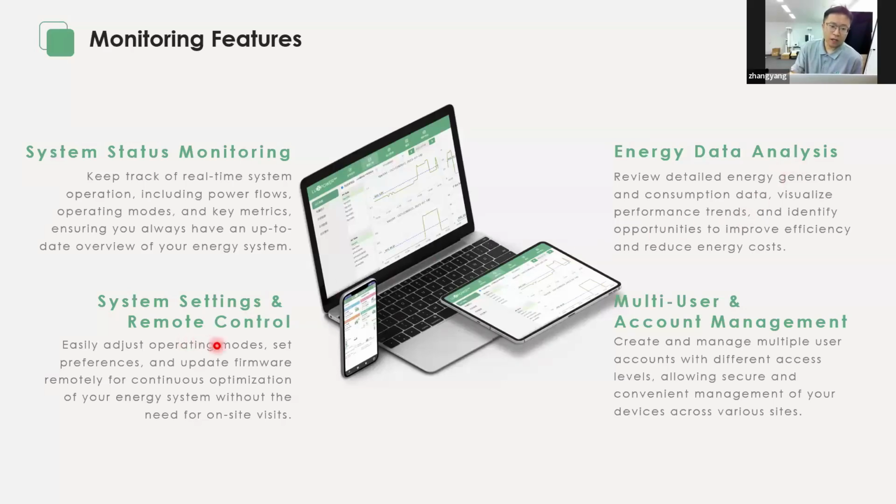And the third part, you can control your monitoring system. You can choose to sell your electricity back from the inverter to the grid, or you can choose your working mode, when the battery should charge and when it should discharge. And if there's a blackout, you can start the EPS to do a switchless transfer from the AC side directly to the EPS side, and it takes maximum only 20 milliseconds, so nobody can notice it.